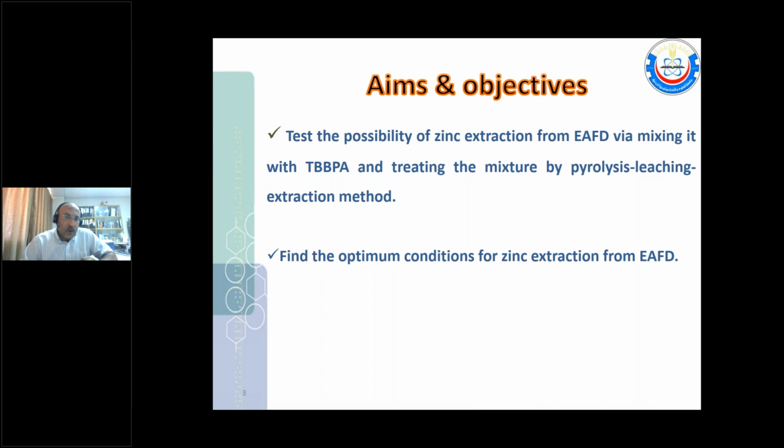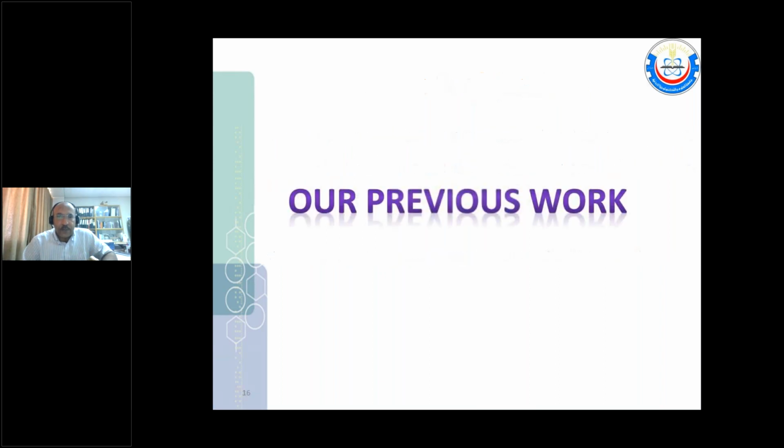Now you can do pyrolysis at high temperature, where you can vaporize these bromides or chlorides, or you do an intermediate temperature treatment, and then you do a conventional hydrometallurgical operation, i.e. leaching. And we aim to use FactSage to model this system and see what will happen.